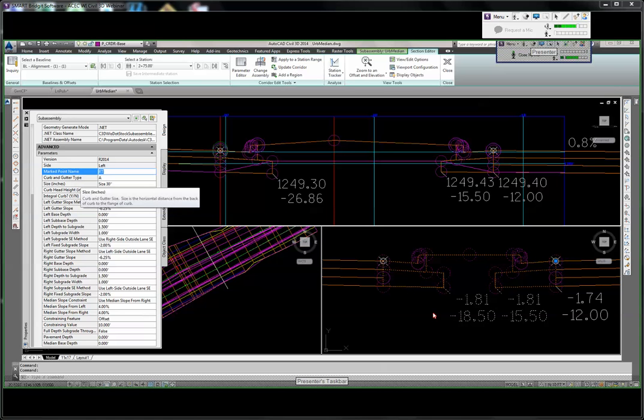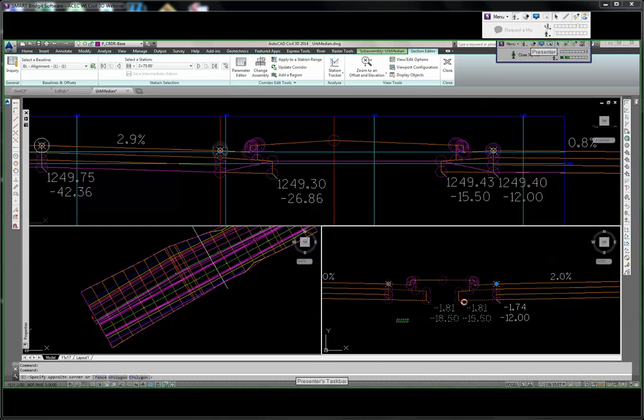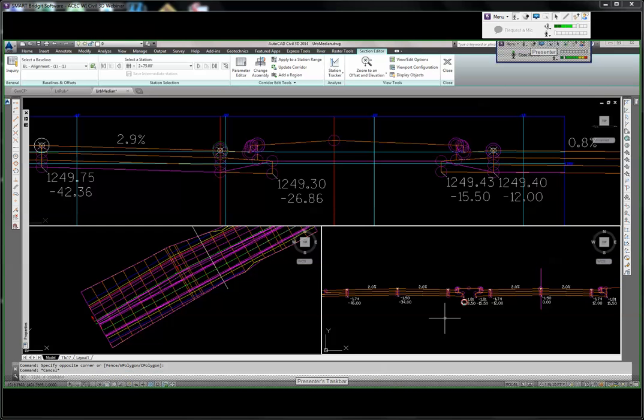What I've done in this particular design: the marked point tools, in Autodesk's world, are generally meant to work with an offset assembly. You would attach it to an assembly off to the side and come backwards with your design towards the original. You're using the marked point as a way to magnetically connect it up or to fill that gap. Well, there's a series of problems. One of the more serious ones is the surface that WISDOT wants cannot be created when you're using an offset assembly.